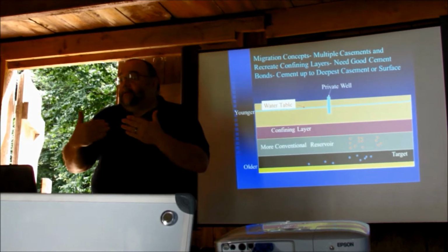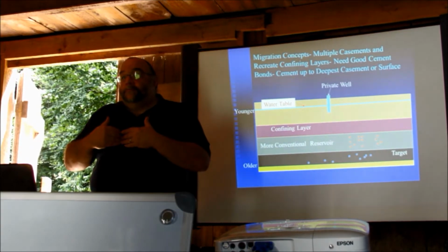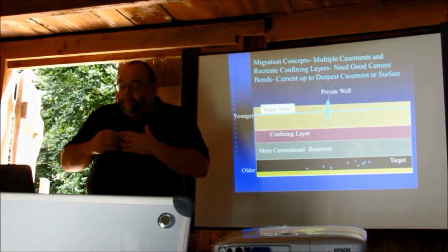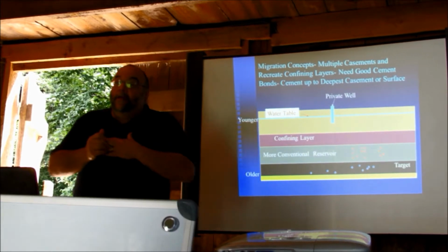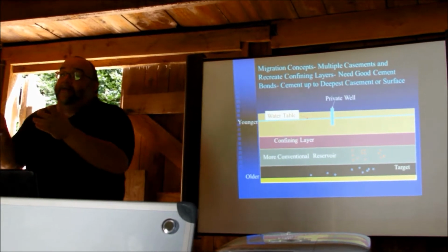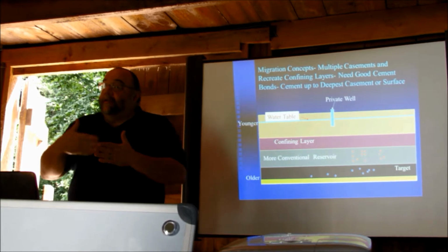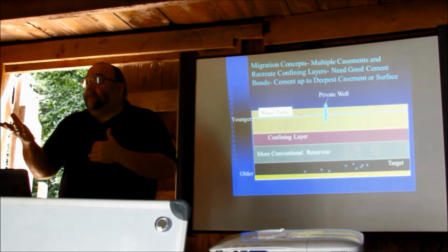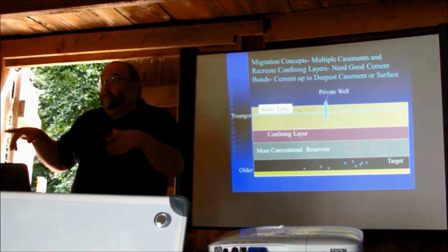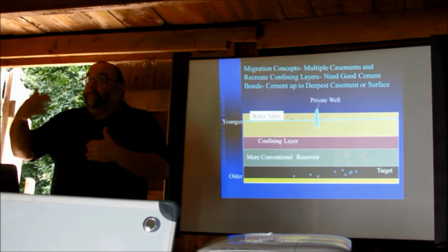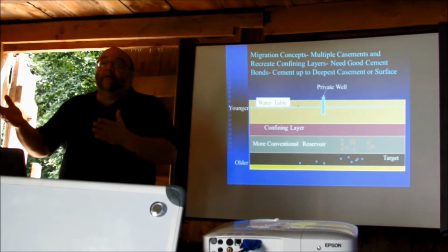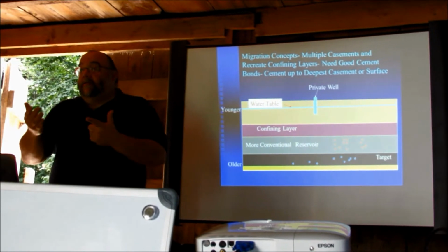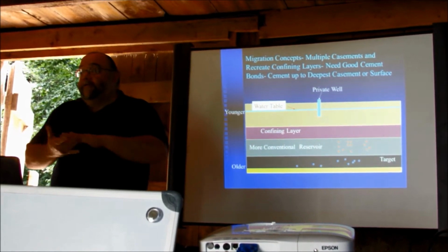That's one of the things we like. Well, it makes sense chemically because of how things decompose and what you normally find together. And where you have that, again, the wells that more likely have that issue are going to be your deeper wells that may have a saline water signature. So for example, your wells here that are deeper with a saline water signature are the ones that are more likely going to have slightly higher levels of alpha, beta, uranium, and radium.